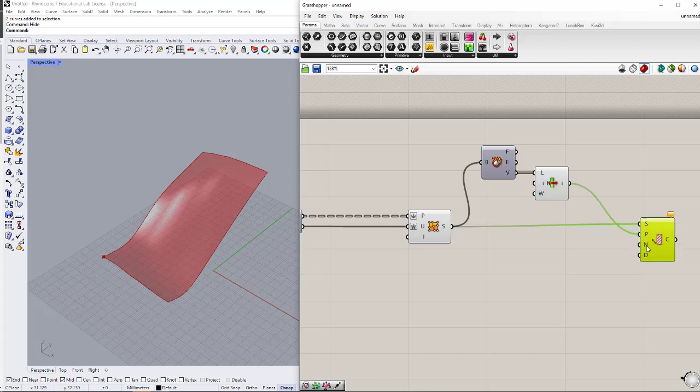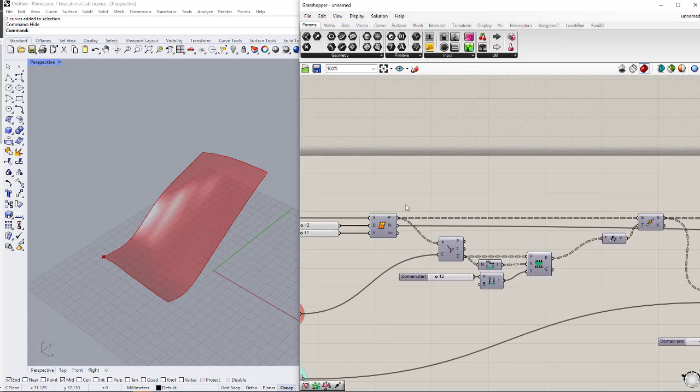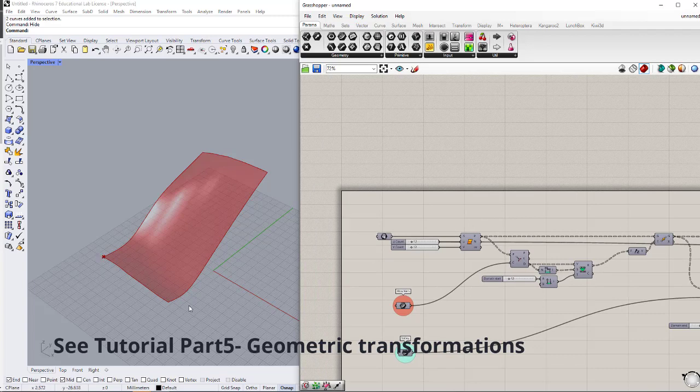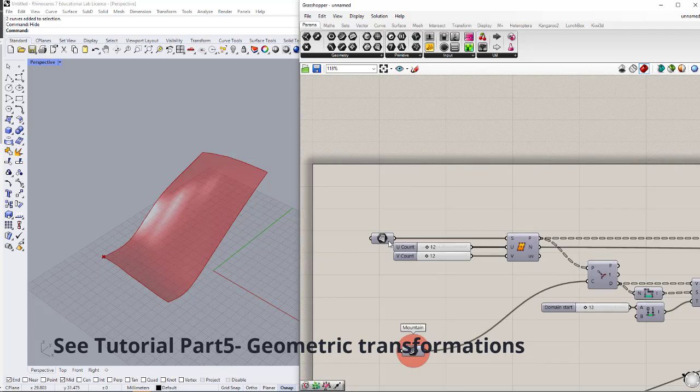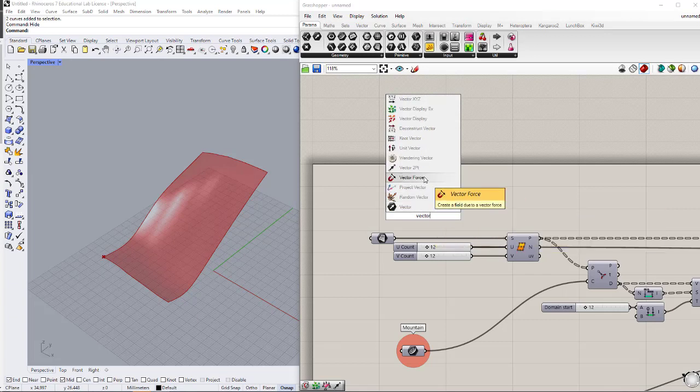And it says what direction you want to make these contours. And I can use a vector to point, which we also spoke about before, and define this vector for it. We can also use an X vector, because we have drawn our surface just in XY, but it's better to use a vector to point to make it work even if the surface has been rotated.